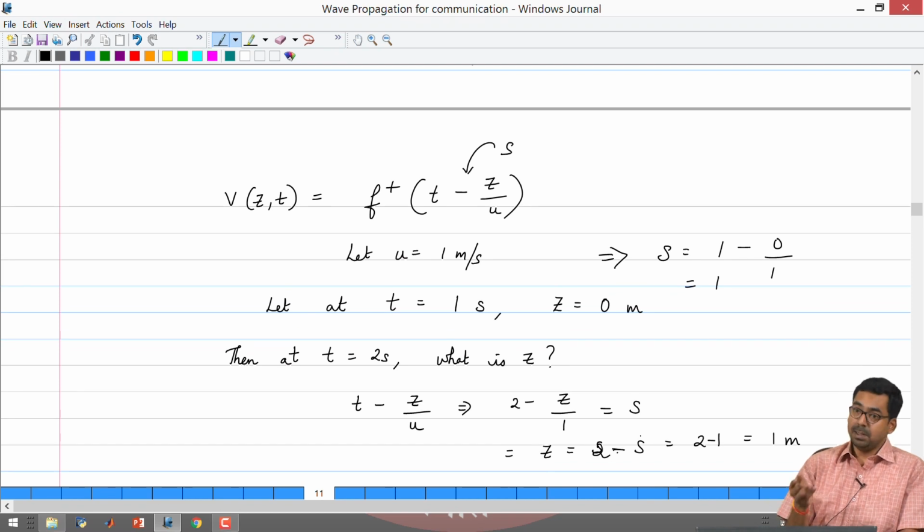Okay. It is also quite possible that the voltage that is travelling forward gets reflected at the load end and travels back, but it has opposite sign. It is quite possible that you are actually sending a voltage pulse from source to sink, but if you are using a multimeter or some other technique to measure the voltage across the transmission line at a given position, it is not uncommon for you to read a 0, because the voltage that is travelling forward may have got inverted in sign and actually travelling backward, all right.